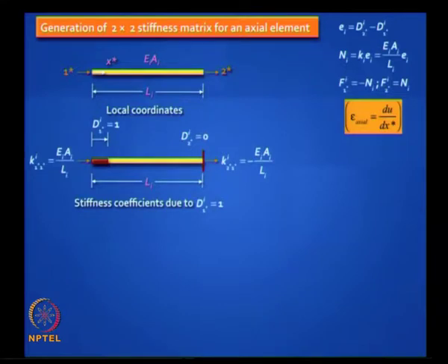What about the deformations? How will the axial displacement vary? It will vary like this. Okay, this is exact. You agree? I am now plotting u of x star, which means any point here I can interpolate the displacement from this end and this end. It will be maximum here and its value equal to unity, and here I prevented the movement, so it is linear.